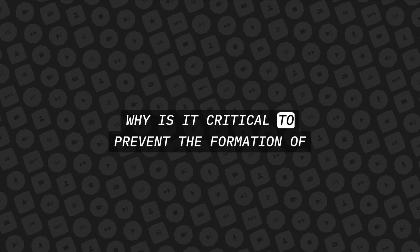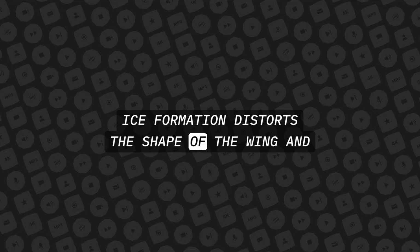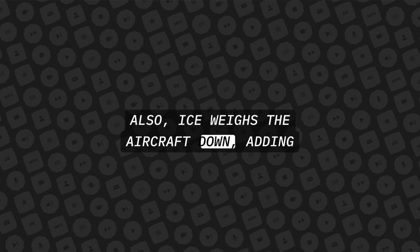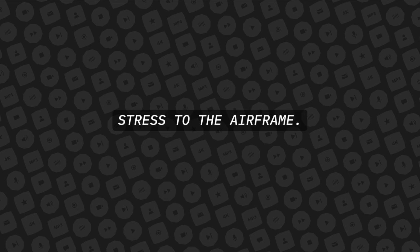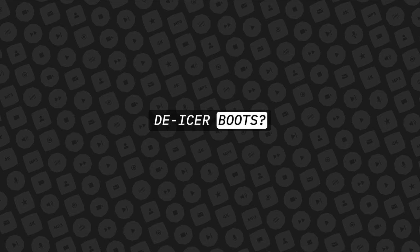Why is it critical to prevent the formation of ice on aircraft wings and control surfaces? Ice formation distorts the shape of the wing and the air flowing over it, reducing aerodynamic lift. Also, ice weighs the aircraft down, adding stress to the airframe. What are two methods of inflating pneumatic de-icer boots?